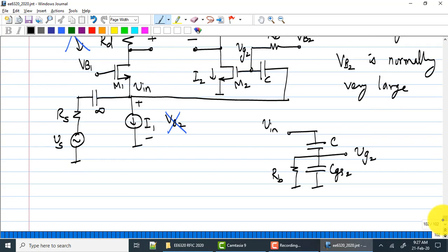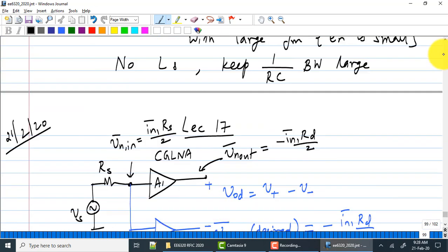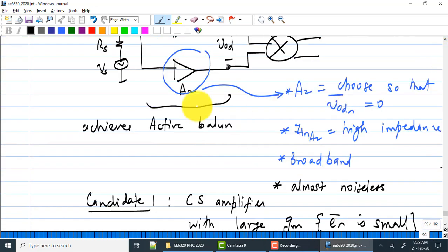You're asking if it is balanced. No, it is not. Of course, it is not, for various reasons. First of all, this is not a 50 ohm output. I understand the confusion, so maybe I'll put it in quotes, because it is not a true balance. It is not matched to 50 ohms at the output.